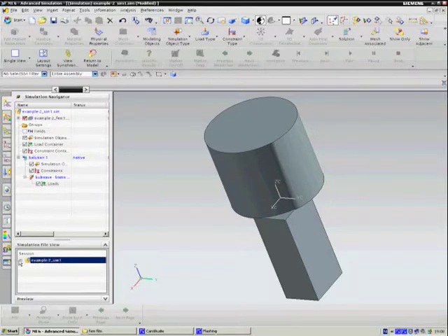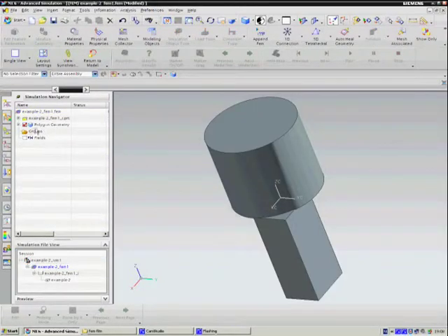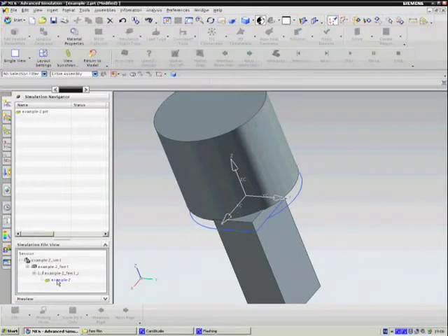The first file, the sim file or simulation file, contains our constraints and the loads. The second file, the FEM file, contains the body, and later on it will also contain the mesh and material properties. The third file is our idealized geometry file. It will contain simplifications. The last file is our part file.